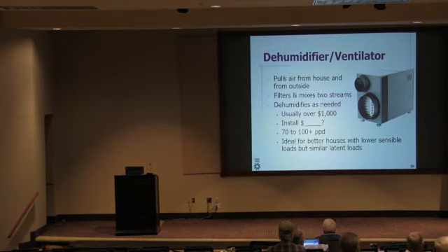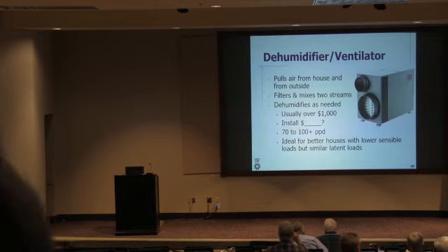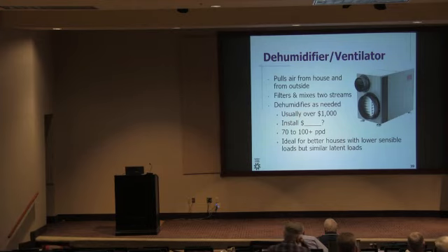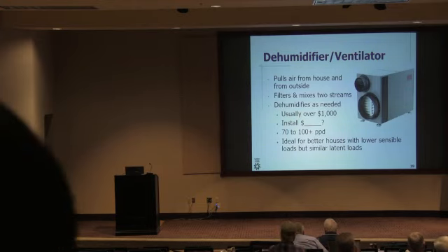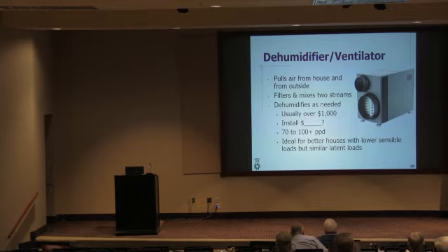Well, you're also introducing moisture into your HVAC system. Terrible building science. Yeah, yeah. And then if you've got internally lined ducts, you've got a recipe for disgustingness. Yeah, we shouldn't put humidifiers on duct systems.